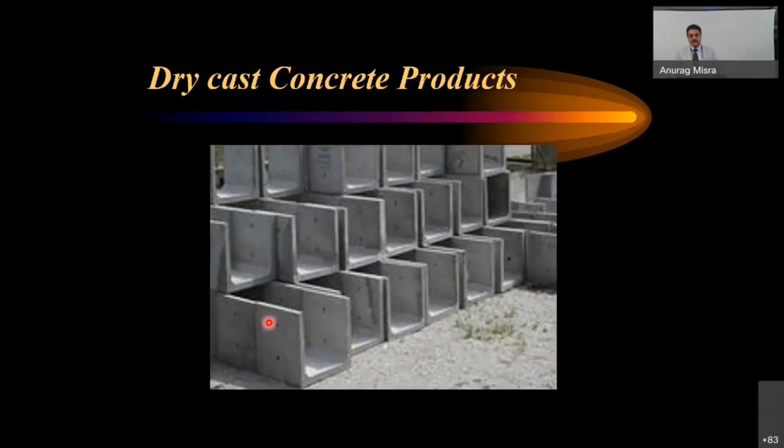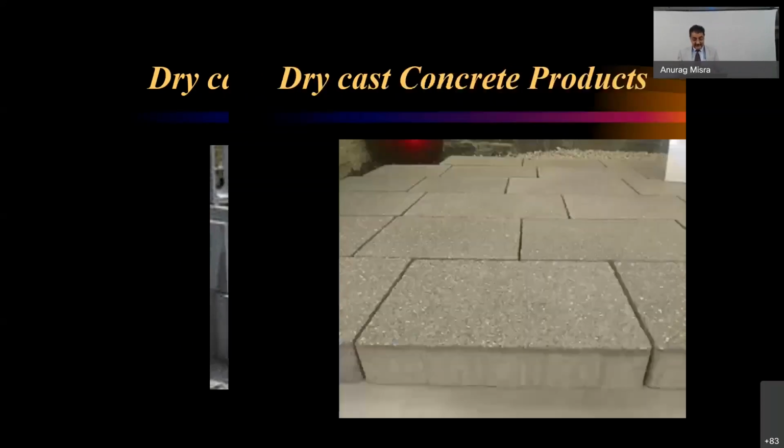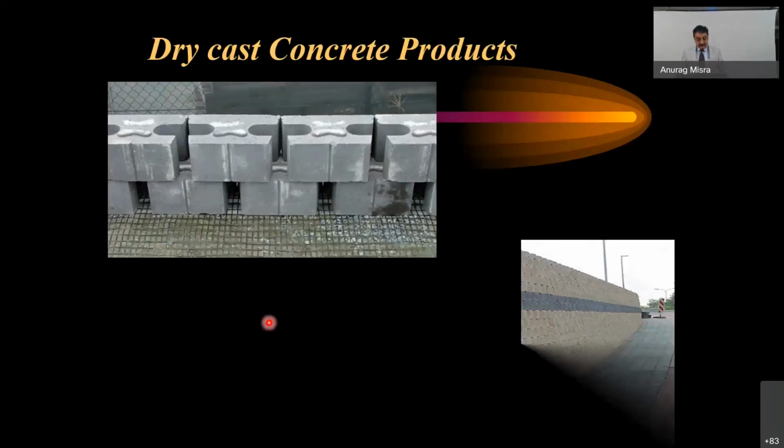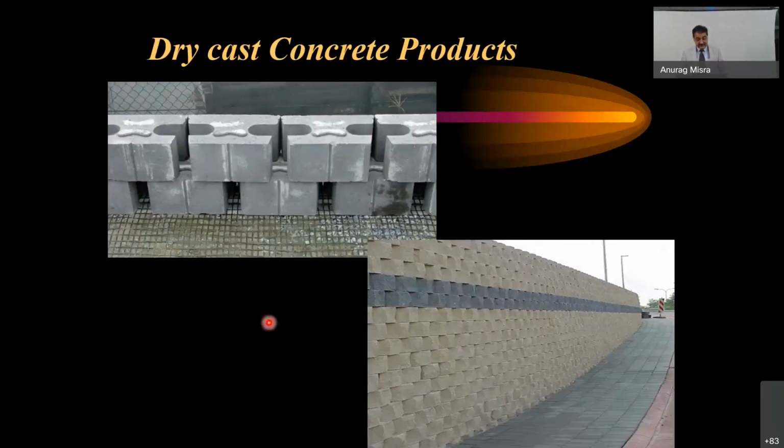Then channel sections also. Within the city also, you just have to dig and pour the PCC and then put these blocks side by side, and you are done with a large area in a day or even a night. In the morning, people come, you have the drain ready. Some slab units or flooring units also, where you want to create a bigger floor in less time, with no jointing, no concreting. You just bring the blocks and arrange them like tiling.